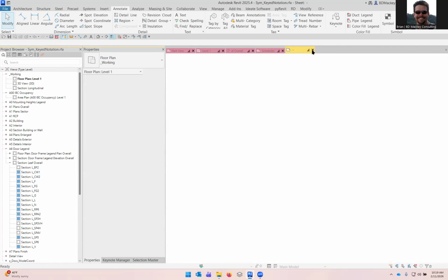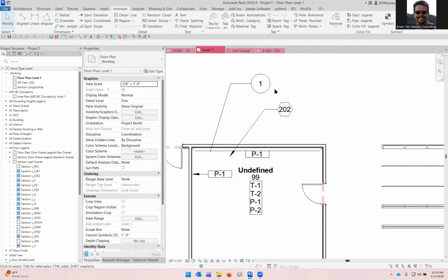Absolutely. If you're detailing, that detail should have been tagged. 100%. I will always say that about detailing. Now, again, I have not sold a single structural engineer on that. They prefer keynotes or want a novel. They want to draw the detail and agree with all detail components and no lines. But they're like, no, no, no. I want to say this is a wood stud wall with 16 inch studs with pressure treated sill plate, blah, blah, blah. And they just want to do one novel next to it and there's no call outs.